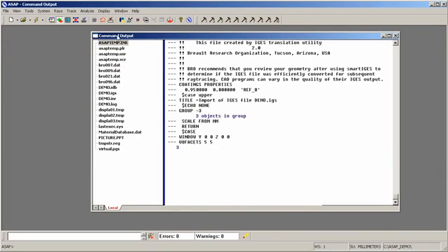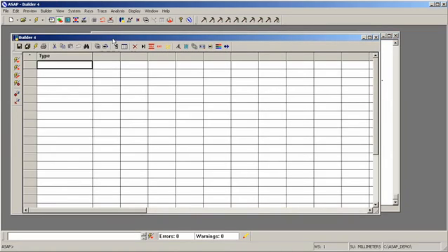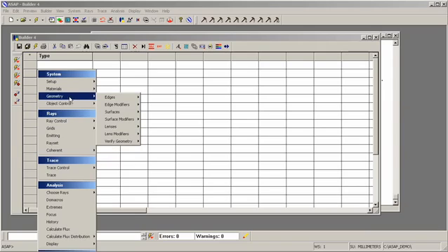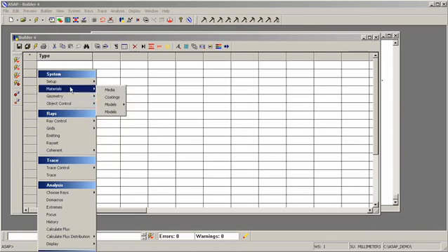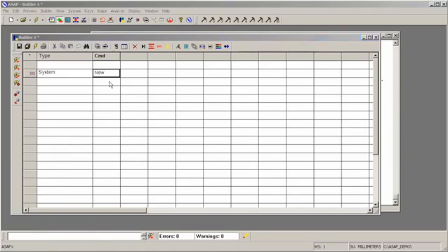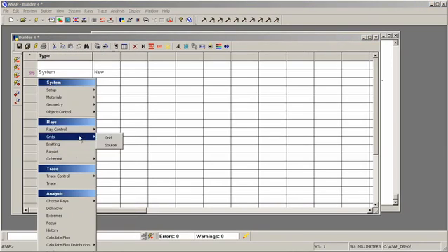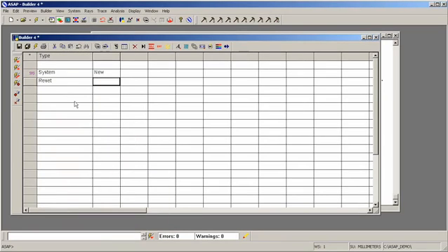The next step is to specify the light source, and we'll do that inside the builder window, the spreadsheet environment that I mentioned earlier. The way the builder window works is the user double clicks in the type column, this pop-up window appears, and depending on whether you want to specify geometry, sources, do a ray trace, you would select these different options here. In this case, we're going to specify a couple initial settings. We're going to tell ASAP that we're starting a new system. I'm going to reset some of my environmental parameters.